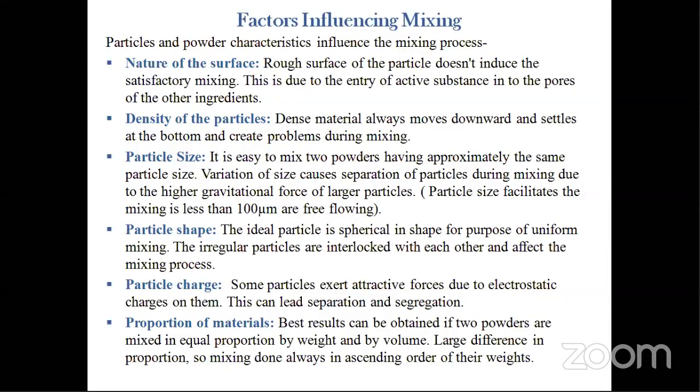Next is the particle charge. Some particles carry different types of charges, electrostatic charges. Particles that have the same charge repel each other, and particles that have opposite charges are connected or attracted to each other. When repelled, uniform mixing does not happen, and when connected, segregation also occurs. So due to the presence of particle charge, problematic situations happen in the mixing process.